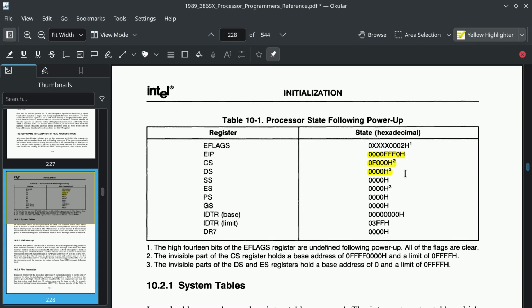Unless you want to place your ROM at the end of the first megabyte, you need to be careful not to touch the code segment register until you're ready, and this is why the 286 and 386 changed the default register values. You can use a relative jump to go anywhere within the current 64 kilobyte segment without touching the segment registers. Now, because we're in the unique situation of having this upper chip select unit activate our ROM for the entire address space, this wouldn't actually be a problem, but it is something to note.